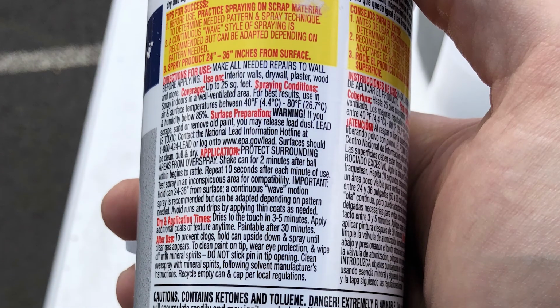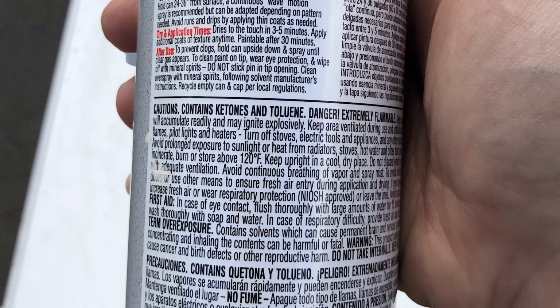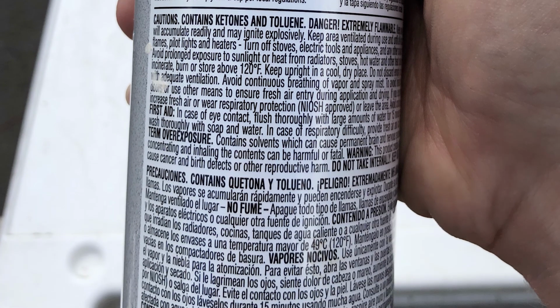In my experience, I find that the thing that's on just about every single chemical is the product identifier, a hazard statement, first aid, and required personal protective equipment. It's usually on everything. So if you write that up and say, these are the items that are going to be on my custom labeling system, you don't have to go back out there and relabel everything. The only thing you need to do is if you do find some chemicals that are missing one of those items, you're going to need to make a custom label for that one and affix it to the chemical. But for the most part, you'll be good to go without having to do any additional work or buy any additional labels.